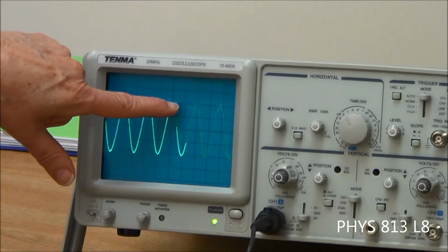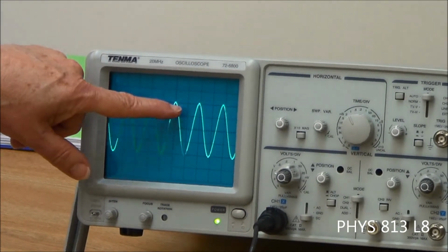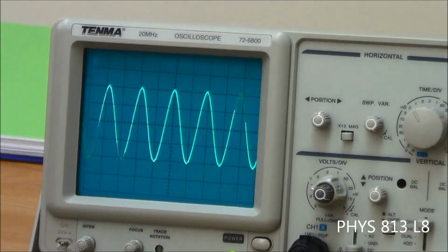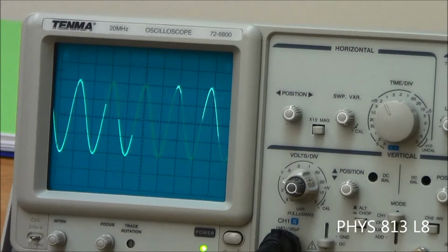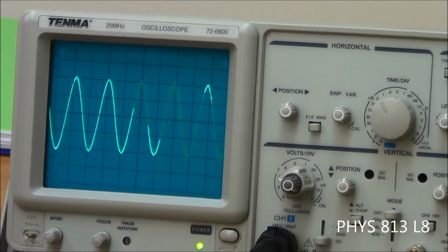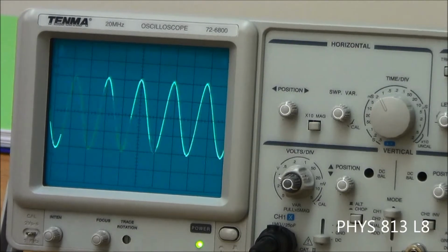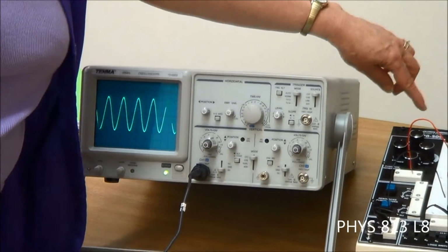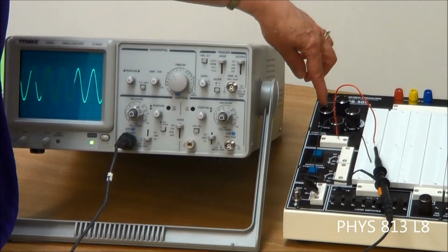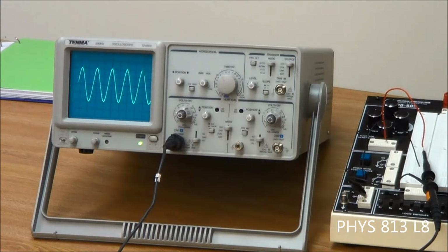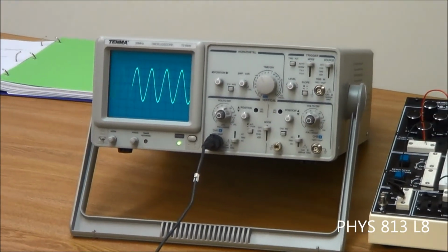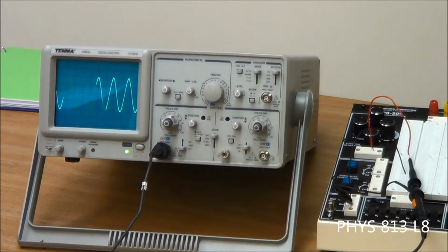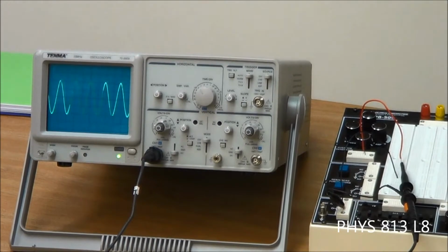So right now I have almost 2 divisions. So 2 times 1 is 2 milliseconds. And if I can do this in my head, 1 divided by 2 milliseconds probably turns out to be about 500. And with this continuous dial about in the middle, and this one up here on 1 kilohertz, then that's reasonable. It should be around 500 hertz. So at this point, you're going to do several things, and it tells you in here, just follow the instructions.